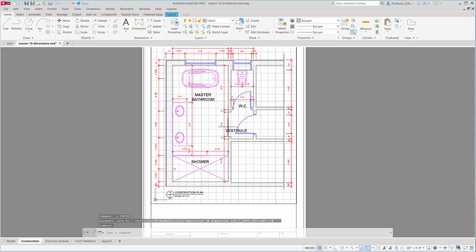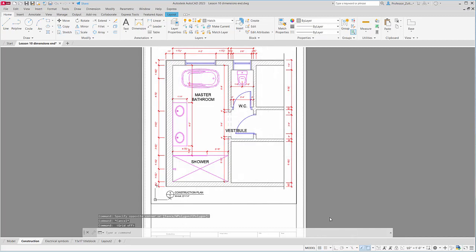There's one last thing I need to do, and that's just change this line type here. So I'm going to double click inside, make sure I'm in the viewport. So there's my XY axis. I'm going to select these two lines and switch them to hidden. I loaded that up earlier. Now it looks like one of them is solid, but it's not. It's landing accidentally right on the grid. And so if I turn off the grid down below, you'll see that it is in fact correct. Now I can press escape, double click outside, and it's done.